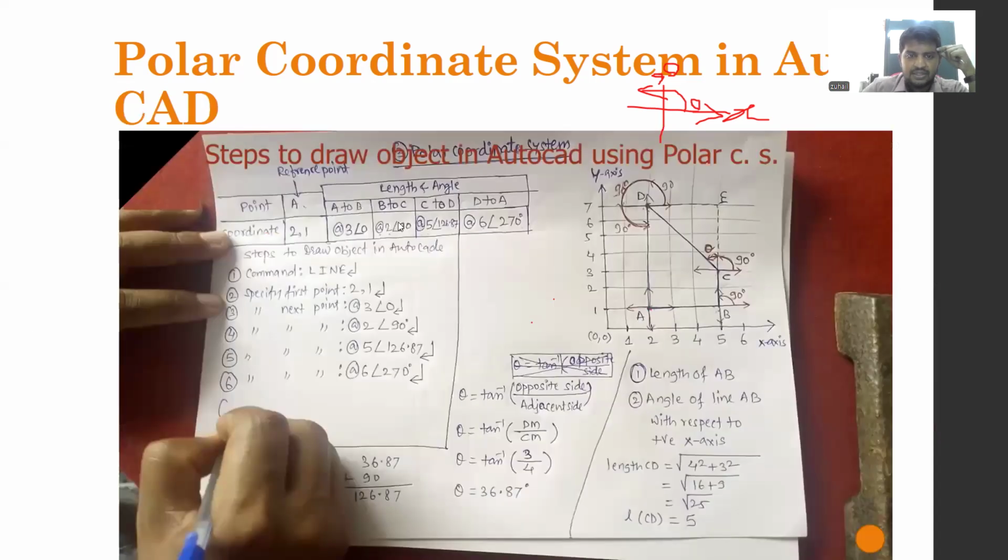Here. For this drawing also, here we are starting from A. So A 2, 1. At, what is the length? 3. 3 less than, here you are putting the length. You are using the length and angle. For the polar coordinate system, you are using the length and angles. So the length 3, so 3 less than, from the keyboard you can press this less than symbol, and 0. This direction is 0. Then enter. Then you will come here.